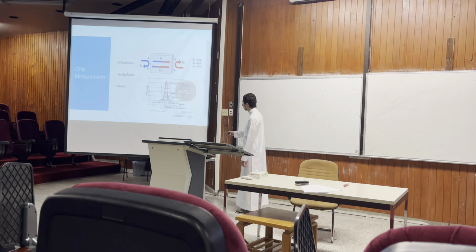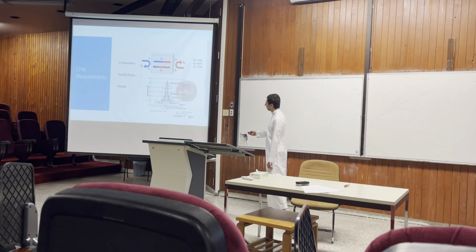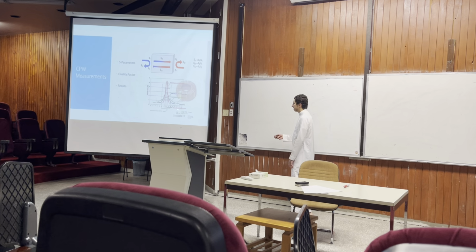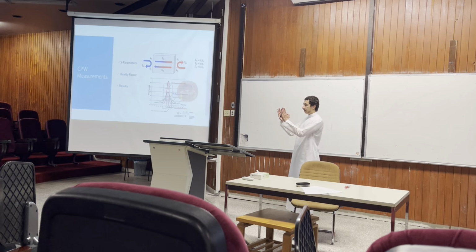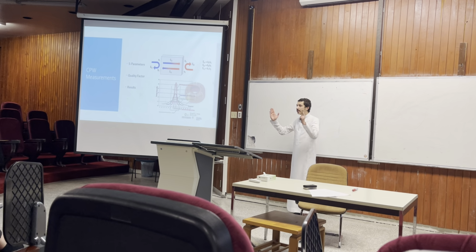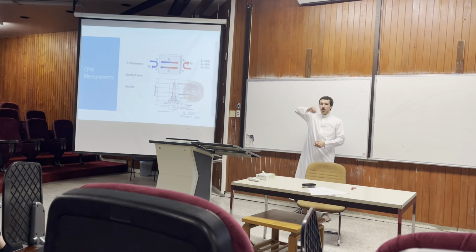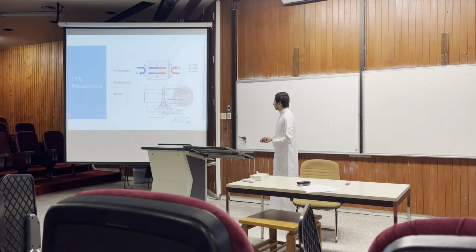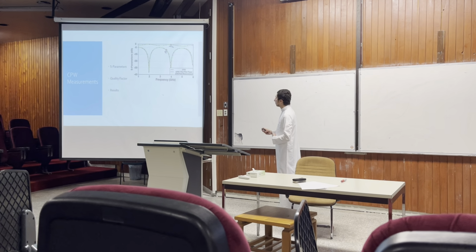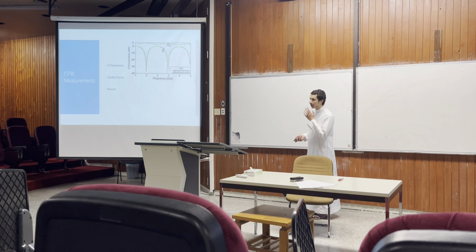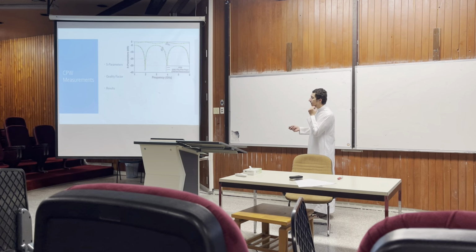And so we would get plots like this of the voltage or the gain or the intensity versus the frequency. And the sharper the peak, the higher what we call the quality factor. Almost like the more ideal the case is, because we expect to have one single resonance frequency peak. And so, ideally, this is a result that we would get. It's a very narrow peak, very sharp.